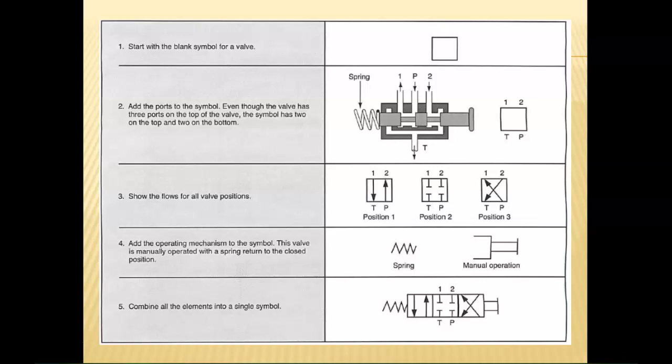Position 2, it could be that you just took your hand off it, but you don't want your actuator to move just because you took your hand away. Does that make sense? It's a neutral, yeah. It's a way of, okay, I need my actuator to stay there for a minute because it's got to hold position while maybe another actuator comes in and bends a piece of metal. It's just a way of saying, okay, this stays here for a second. I don't want it to lose pressure because I took my hand away. But at the same time, I don't need it to continually add pressure.